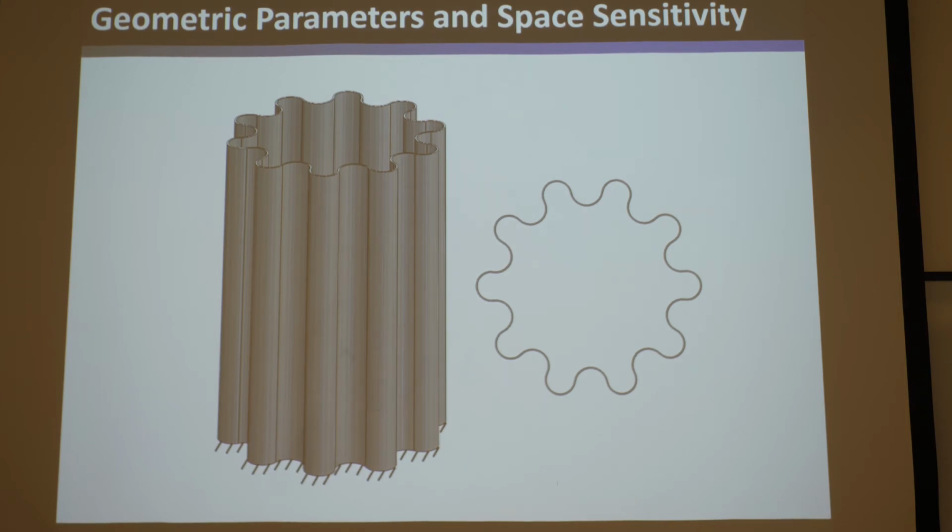Completely different quantities, and then again, who says how much larger one stiffness needs to be than another stiffness in another direction to be considered constrained versus not constrained? That's just as wishy-washy. So no one really has rigorous definitions of degrees of freedom when it comes to compliant systems, but all three definitions are kind of useful to think about, to try and constrain certain directions as much as possible while allowing high compliance and low constraint in other directions as much as possible.